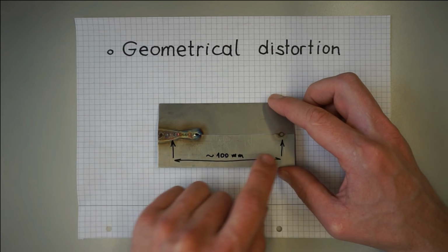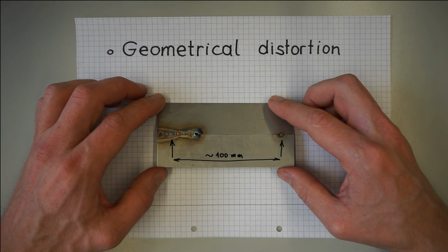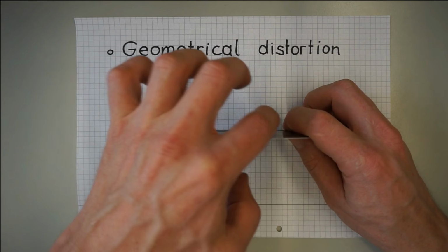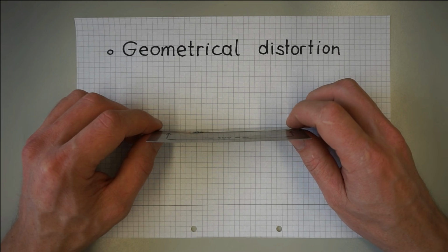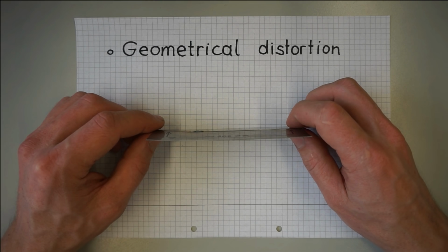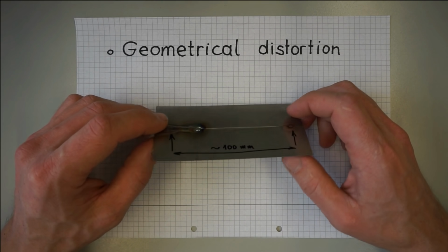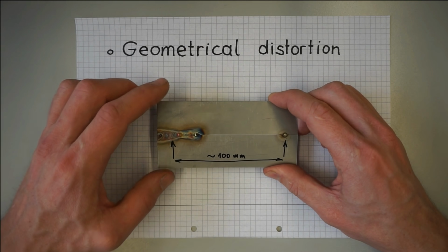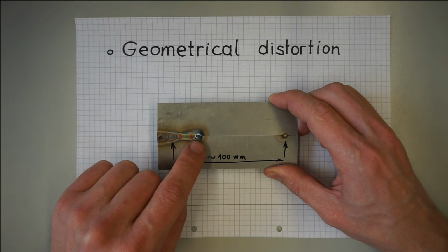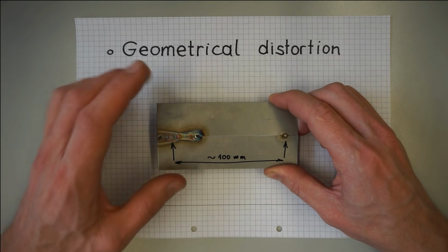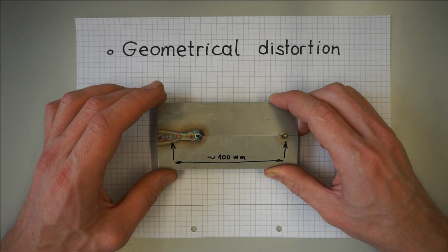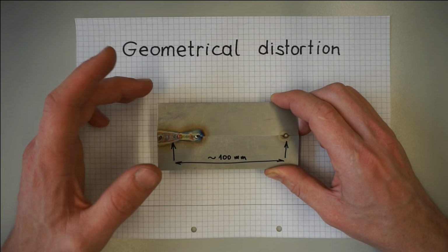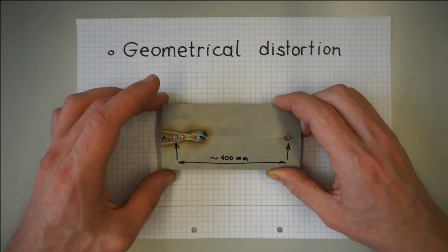I've marked the tack spacing, which was roughly 100 mm, and you can see nicely how the sheets try to buckle between the tacks. Obviously this is local distortion, but it most probably will cause some overall distortion as well. You also see that the sample tried as a consequence of buckling to keyhole on me, but that's not the point here. Obviously the tack spacing here was insufficient, meaning not close enough.